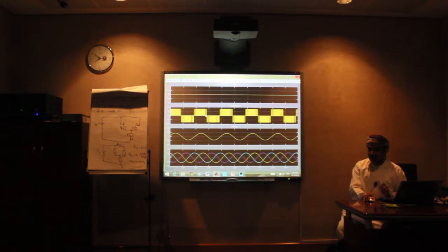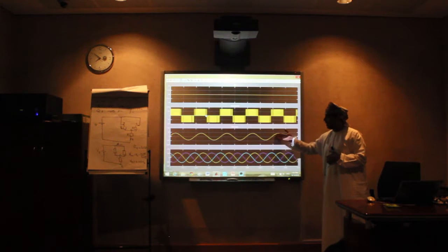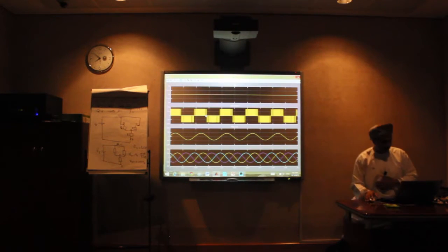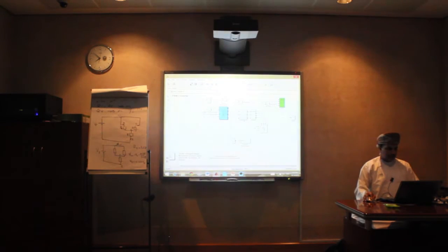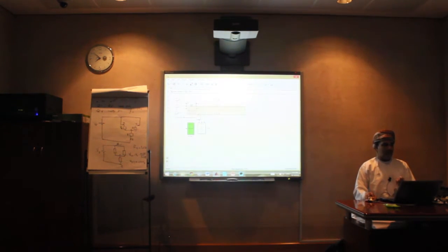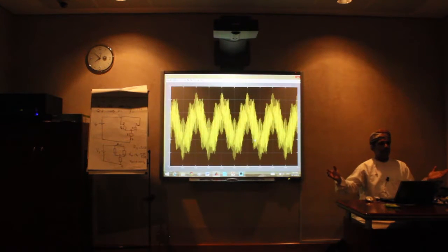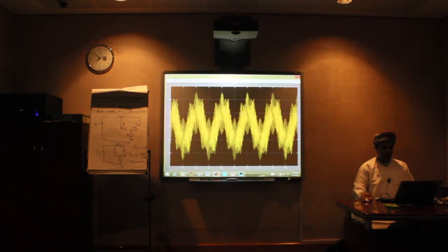Now, I have this signal, right? I need to filter it in order to get an AC like this. Therefore, I will pass this one through the filter. So this is my filter, and it's an LC filter, which is a low pass filter. Look here, it consists of an inductor and a capacitor. When you connect the filter, as you have seen yesterday, it absorbs the noise, right? Those harmonics will be absorbed by this filter, see? And you are left with this output.